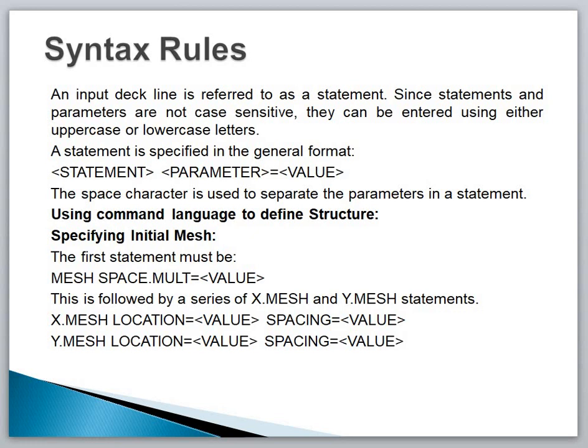Any input line in DeckBuild is referred to as a statement, just as go atlas. Go atlas is a statement. Statements and parameters are not case sensitive. You can write them in uppercase or lowercase letters. They can be entered using either uppercase or lowercase letters.